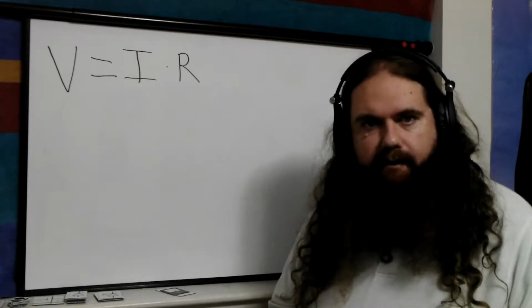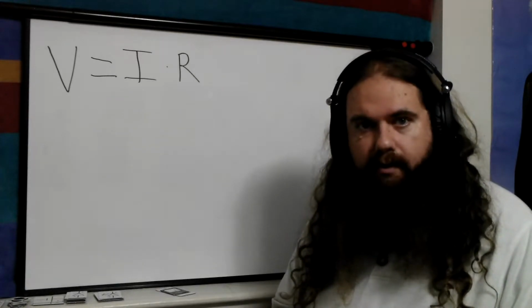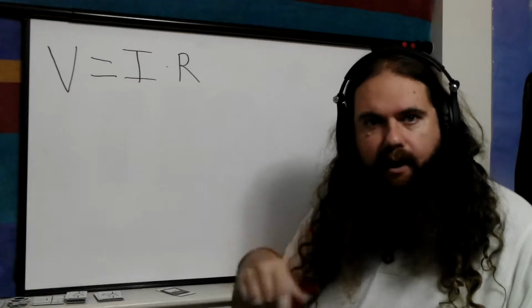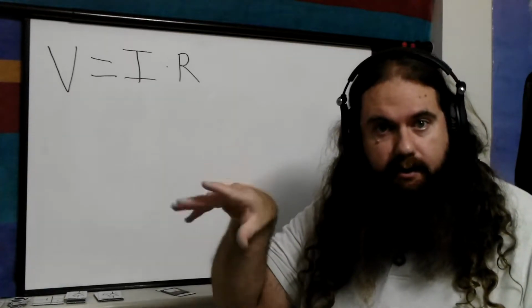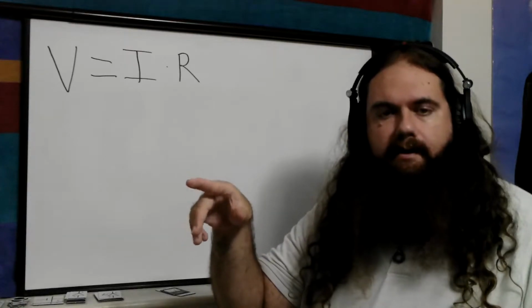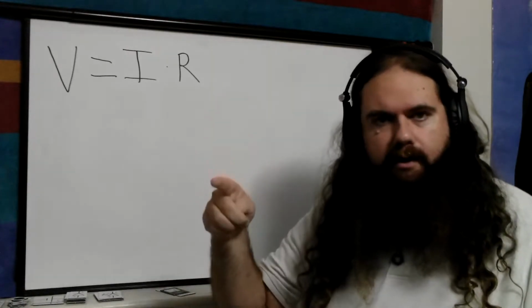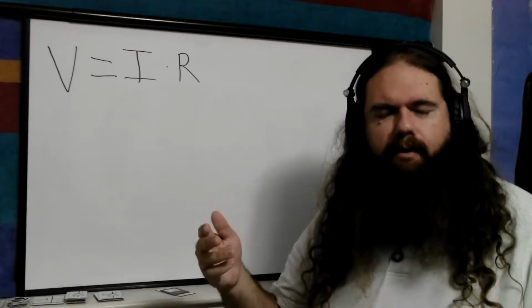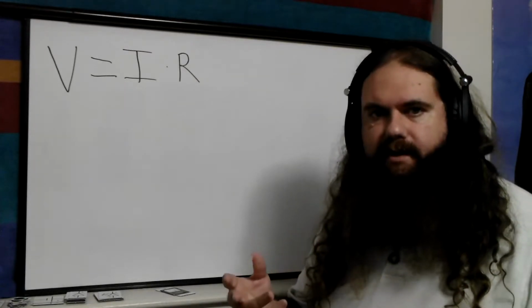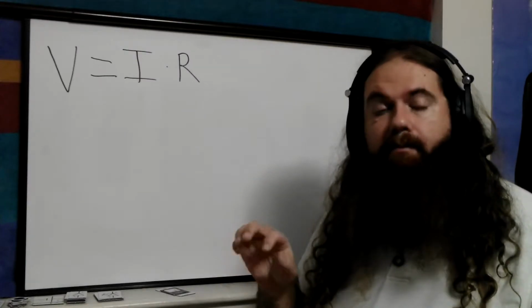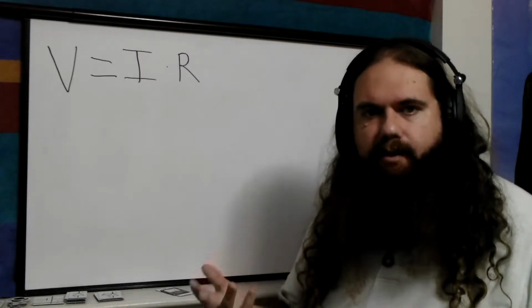A diode, for example, has a forward voltage drop, so you can take that voltage out of that part of the circuit, calculate the resistance remaining using Ohm's law, and then you get the total current throughout that part of the circuit, which you can then put back into Ohm's law to calculate the effective resistance. Not the real resistance, but basically how much it is in practice.